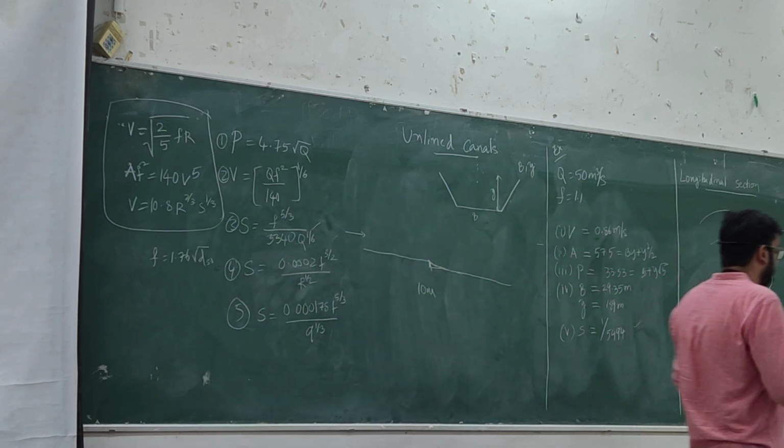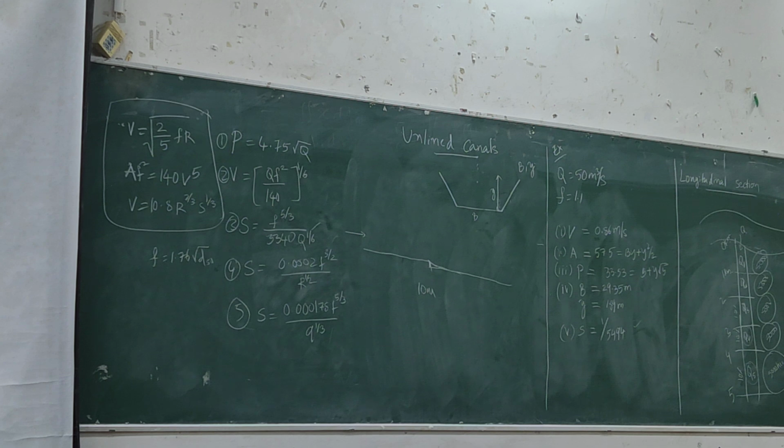So to bring in the context of Unit 1, in Unit 1 we discussed different types of crops and the water requirements for crops, right? And when we want to design a channel or a canal, this Q, or let's say I have 5,000 hectares here at the bottom, and the discharge is Q5. So this discharge Q5 comes from the water requirements for the crops. Whatever we have learned in duty and delta in the first unit, we will be using those concepts to calculate what discharge is required at this section.